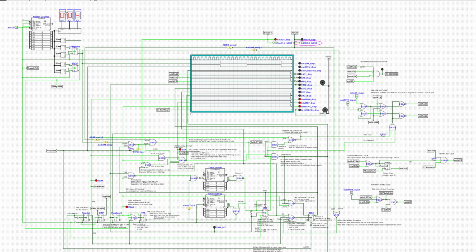Alright, I hope you had time to hit the bar, because in the second part of this video we are going to deep dive into the noodle logic. So here's the grand refresh logic circuitry. You recognize my little generator in the top. So here's the clock, and then I generate STM using the technique I demonstrated in my Logisim video. So I have clock, STM, A14 and address as my input mostly.